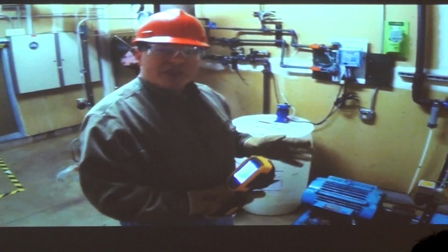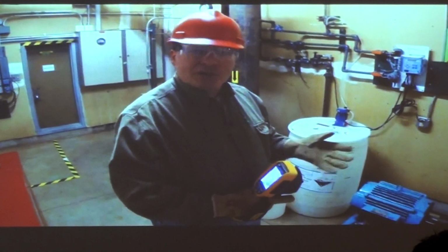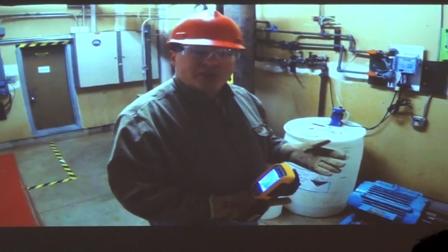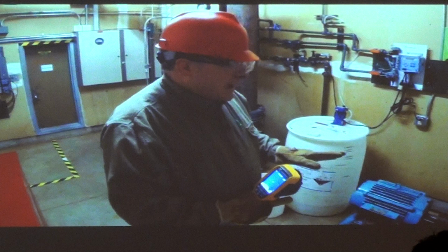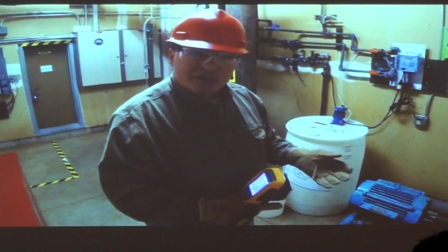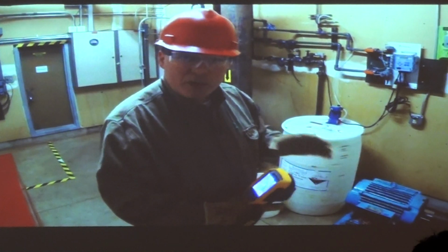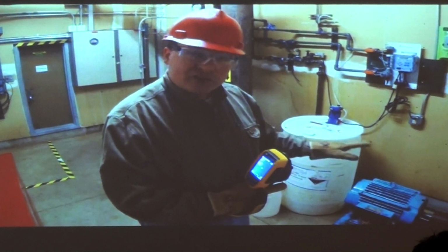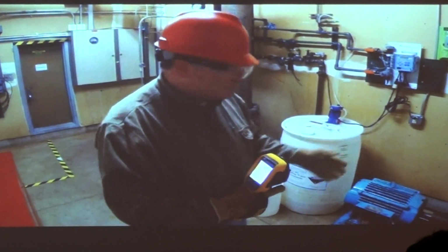Any of these problems that I've discussed before is a great opportunity to say, okay, well, what do I do next? I've discovered something that may be draining energy, draining money out of my budget. How do we fix it? Well, you have to be able to diagnose it. So a lot of things, if you're finding a problem with the thermal imager, and it looks like it's bearing related or coupling related, you can then use a vibration tester.